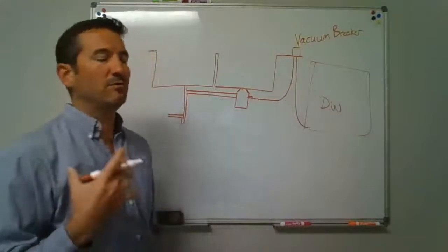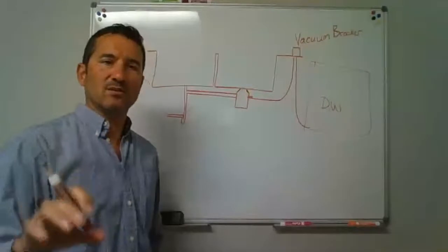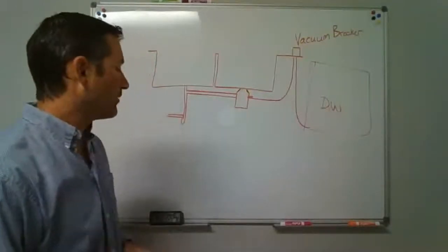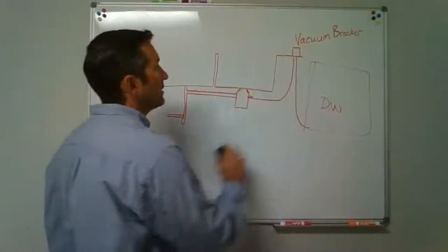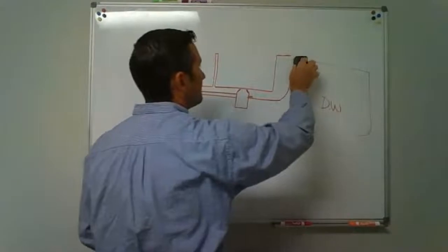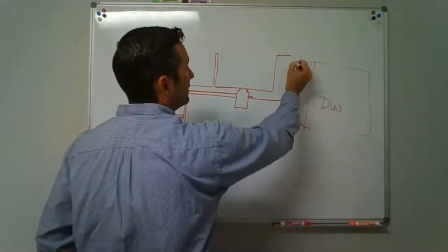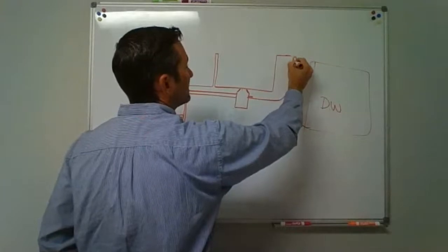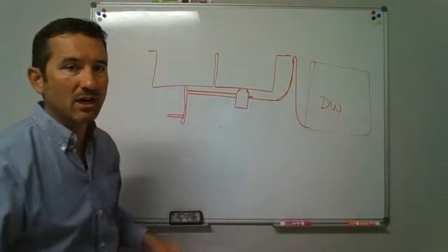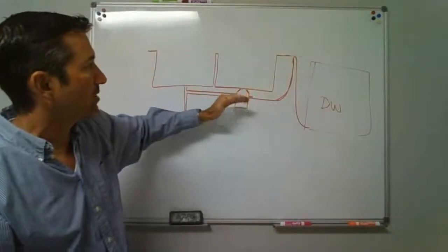Like I said, if you get into an older kitchen and you see this funny looking thing mounted to the top of your countertop up there, you might say, what is that? It could be a vacuum breaker. Now, another place that they give you is to say, or if you don't do that, you can take and run the drain line up and it gets connected or attached to the bottom side of the countertop. So basically you could just flex it up, and then bring it back down.